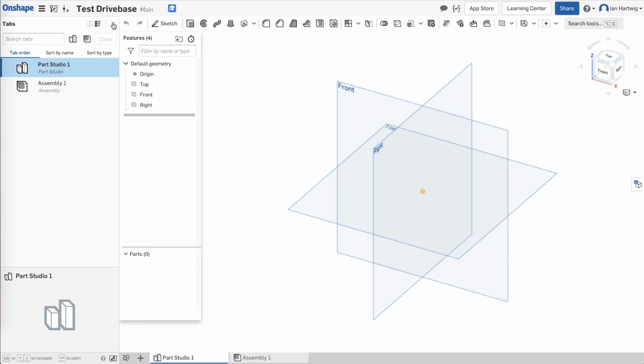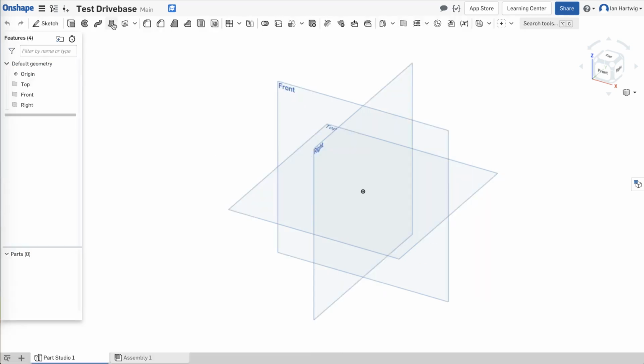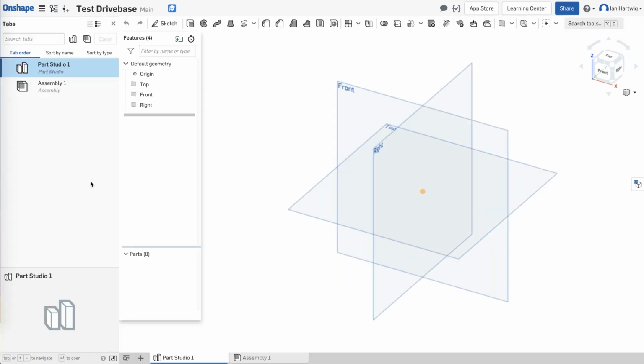I noticed that in some larger assemblies, like if you look at the Citrus Circuits robot, to make some things easier, they put a lot of their robot into one Onshape file. That means they have hundreds of tabs across the bottom. So to make this a lot simpler to view, you can open that extra window by clicking the Toggle Tab Manager button on the bottom. And you can see that it helpfully adds extra text telling you to use Alt-T as the shortcut. So I'm going to leave this open.